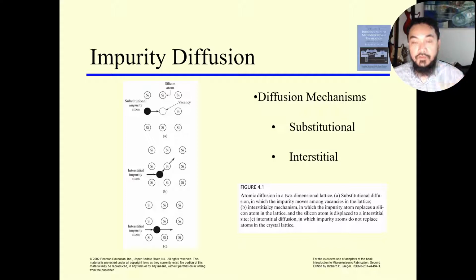Diffusion in essence is the same thing, whereby you have your wafer and you heat it up at very high temperature, ranging between 900 to in excess of 1200 degrees Celsius, with the addition of a thin layer of impurity atoms on top of your wafer. These impurity atoms will start to diffuse into the wafer. You can imagine that the wafer is absorbing these impurity atoms.